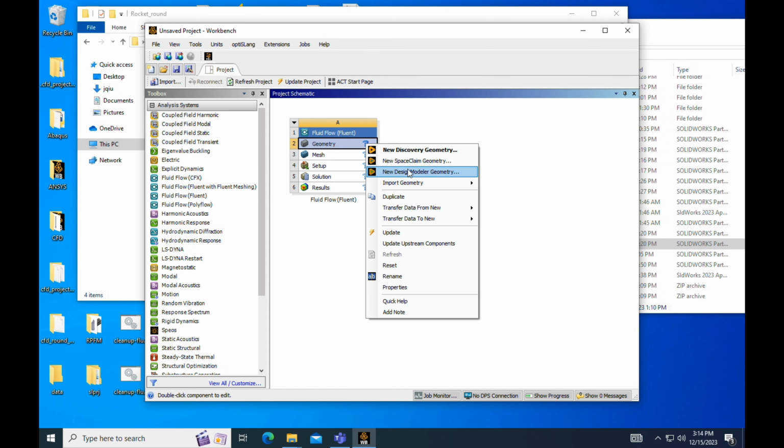And then for the mesh outside of the original mesh, we're going to make that 0.5, and the outermost mesh, each element will be 1 millimeter. Then we'll generate our mesh. This part takes a bit, so we're gonna skip ahead to when it's finished. Now it's done, and we can see that the resolution of our mesh changes the closer we get to the rocket. And we notice that the mesh looks pretty good. There's not a lot of obtuse shapes or anything too crazy.